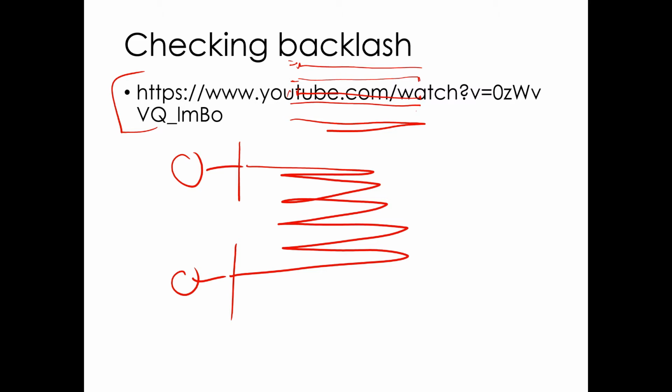Errors that accumulate, like when you're doing integration mathematically in a digital computer, you lose some information when you integrate. You lose precision at some point because you're representing things as a finite number of bits. In that case you're actually losing information, and your integral gradually gets more and more wrong as time goes on. That's a problem. That's an accumulating source of error. If you're using steppers and you miss steps, that's an accumulating source of error. Those are the things that are really scary in servo control machinery. Error that just happens at a step and then gets undone, like backlash, is something we have to worry about, but it's relatively easy to fix.